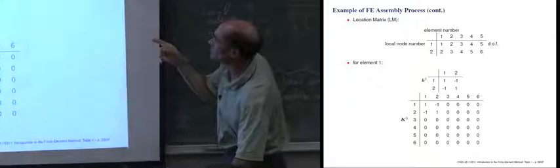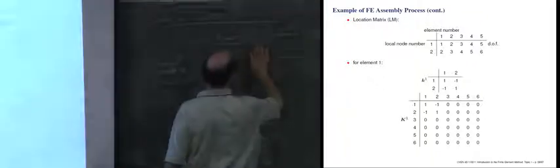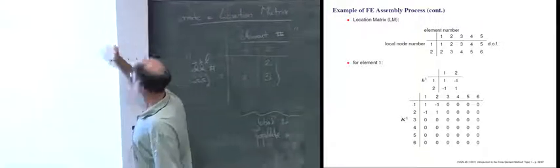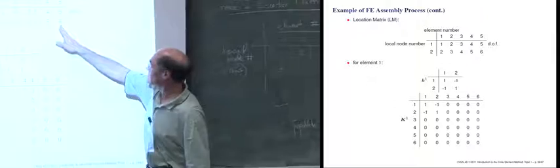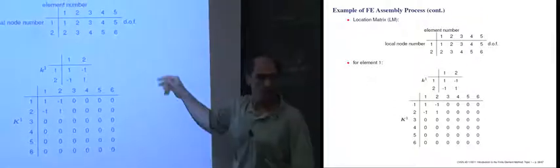Okay, so what we just talked about on the board with respect to that 2-element mesh, now we have a 5-element mesh. So now we have, instead of 2 columns, we have 3, 4, and 5 columns. And instead of ending at global degree of freedom 3, we go all the way up to global degree of freedom 6. So you can see how that populates along.